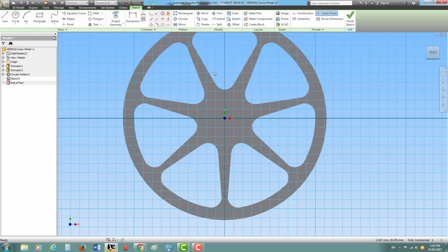So now that I've given you that little bit of background, I want to make a hexagonal hole. You notice there's no hexagon function, but there is a polygon function. So I click on it, and hex stands for 6, so I'm going to choose 6, because it's already written there. Click on done, and move my mouse around. Whoops, sorry, once again, we've got to click on polygon. You don't click on done.